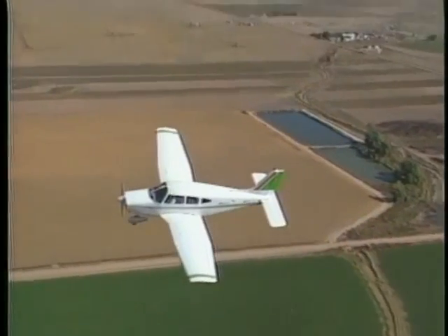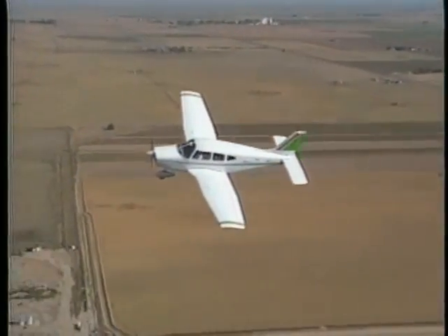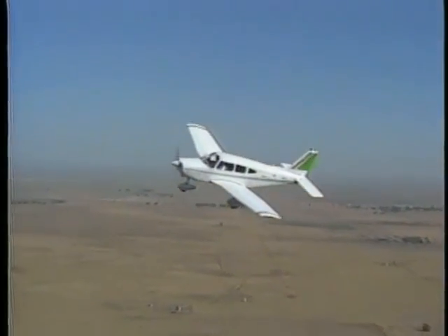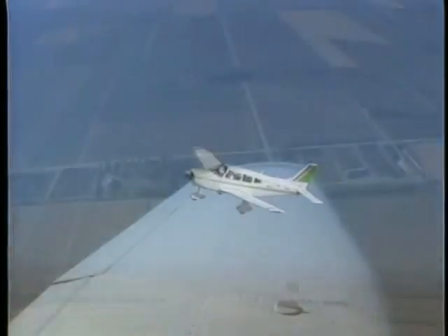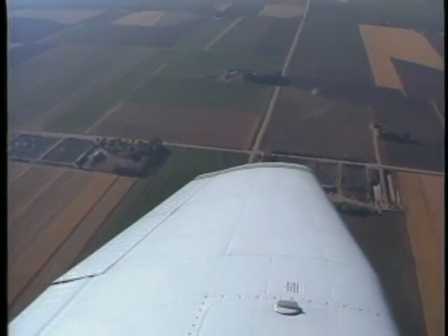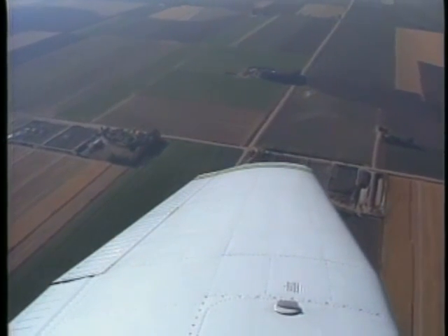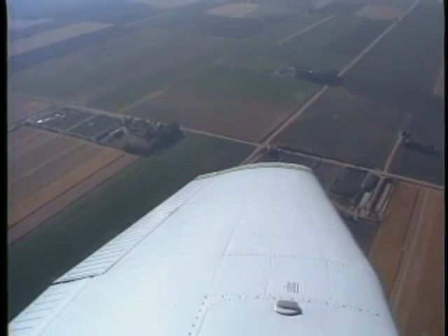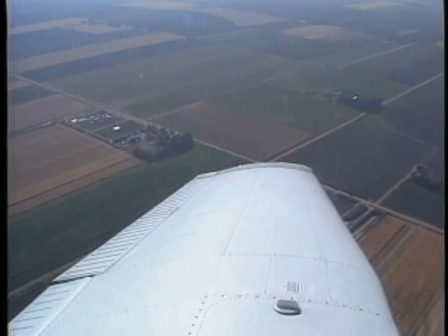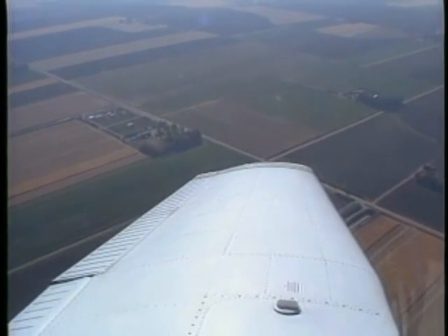As you proceed around the first pylon, your ground speed increases, so gradually raise the nose to keep the reference point aligned with the pylon. If you don't initiate the climb, the reference point moves ahead of the pylon. This means you're below the pivotal altitude. Remember, increased ground speed means an increase in the pivotal altitude.